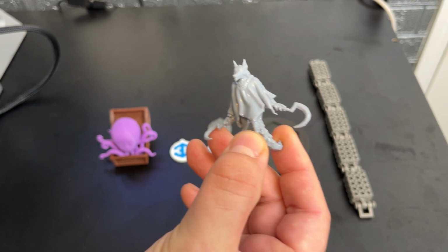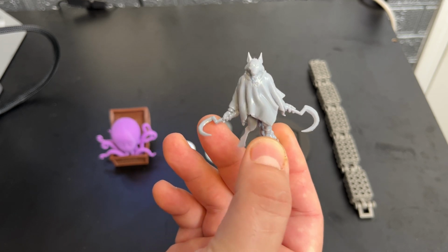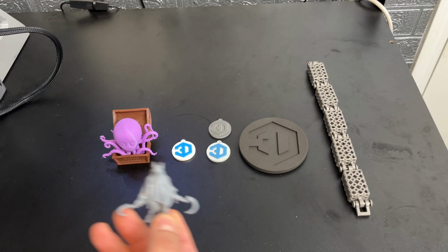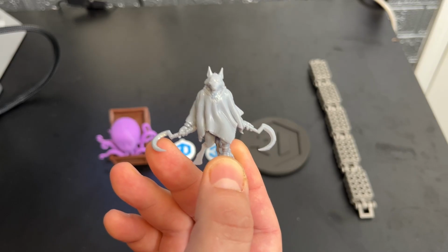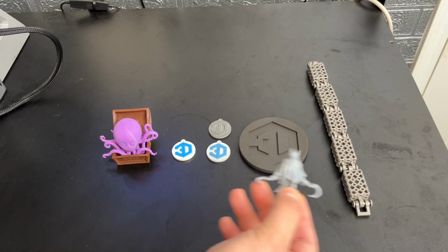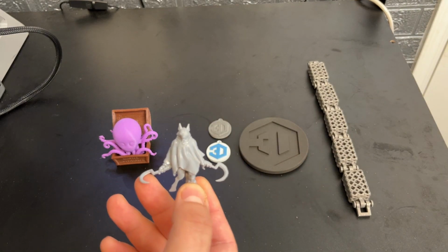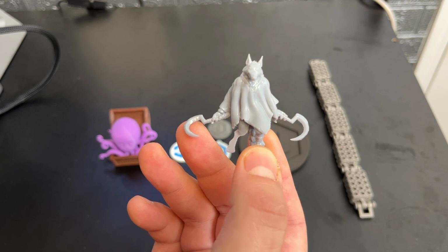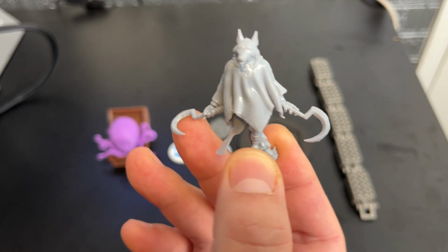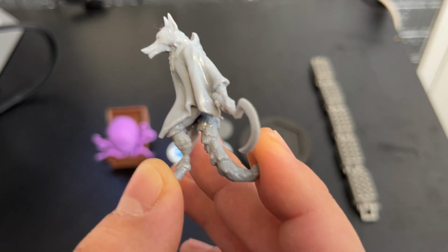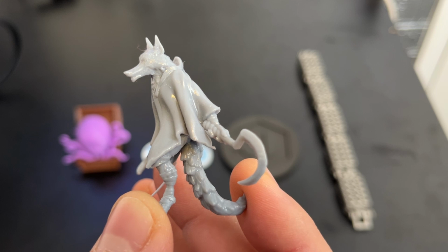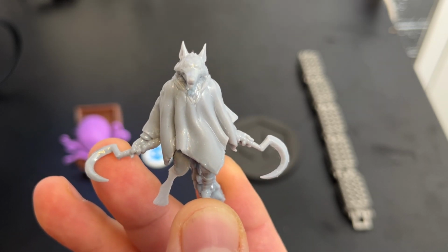And the common uses for this is for high detailed models, jewelry, dental applications, and this is the weakest of all the processes over here. So this produces parts with lower strength and is more brittle. And remember that this is in order from weakest to strongest processes in terms of parts production. And this is a photopolymer resin, and it offers high detail and smooth finishes, but requires careful handling because it's so brittle. But nonetheless, you can see how smooth it is. There was no post-processing done to this, and you get high levels of detail, great for miniatures as well.